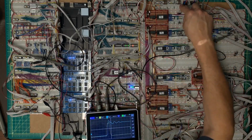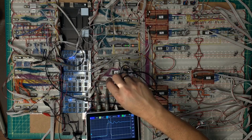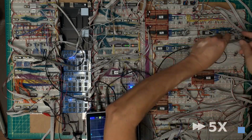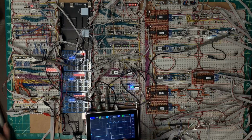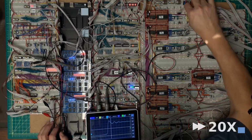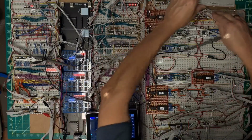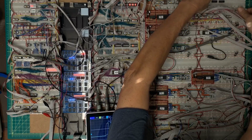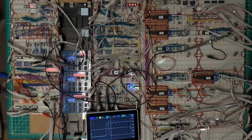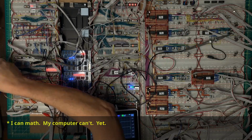So now I've managed to bring the latch forward. The question now is do I have enough of a delay here? I don't need to change that. So the question is am I outputting the correct stuff? I am not outputting the correct stuff. Let's try an absolutely obscene amount of delay here and see if I can't get this working properly. Okay, here are 18 more inverters. Yeah, I said obscene. So 24 and 18, the 42 inverters that I would have in here built into this delay.